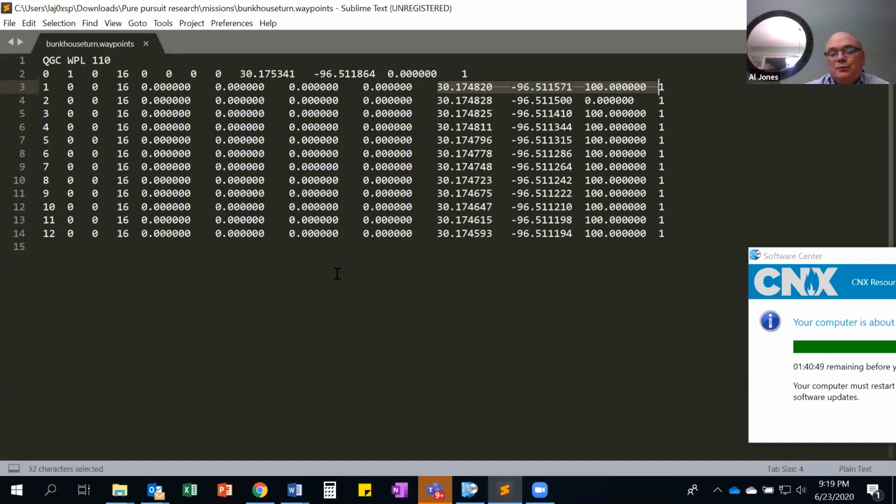I'm just trying to wrap my head around step one: test what the cross-track error is running a simple A/B line, and is the physical steering control reasonably precise? And then step two, once the steering is tuned and cross-track error is within some tolerable degree of measure, feed it 200 waypoints and go cut a hayfield.